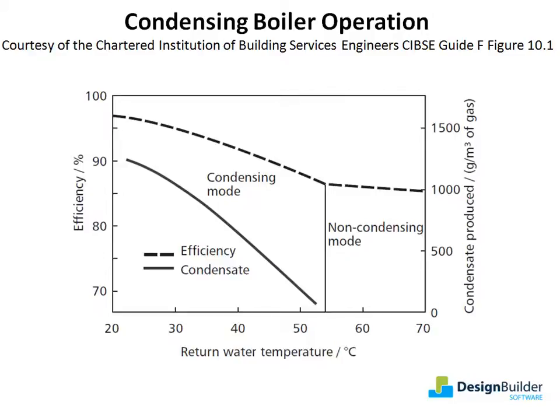You can see from this indicative boiler operation graph that the lower water return temperatures enable condensing boilers to operate in condensing mode more often, resulting in higher seasonal efficiencies. When using more insulating floor surfaces such as wood, you may need to consider increasing the flow temperature to overcome the additional resistance to heat transfer. Underfloor heating can be used with most floor finishes, but is best with concrete and stone tiles, i.e. exposed thermal mass with good conductivity and low surface resistance.